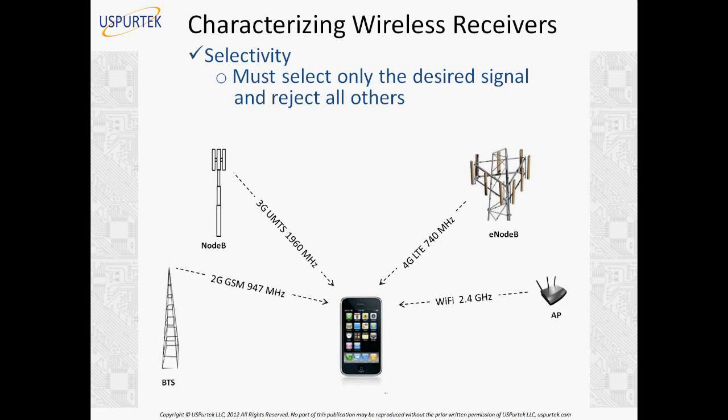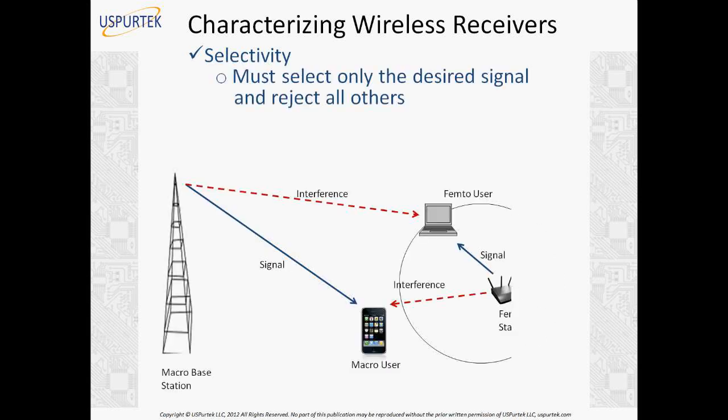Well, there is another scenario. These days this work is going on in the industry. You have macro cells, which are traditional macro cells. We have a base station which covers a certain area, maybe 30 or 35 kilometers. Then you have femto cells. Femto cells are inside the building. So we have a macro base station and you have a femto base station here. A femto base station covers a smaller area, maybe 10, 20 or 50 meters. Now, the macro cells and the femto cells are actually overlaid. The same carrier supports the femto cells as the macro cells.